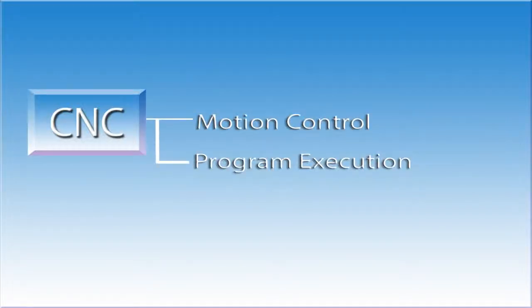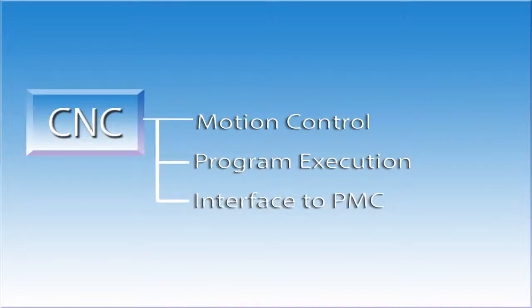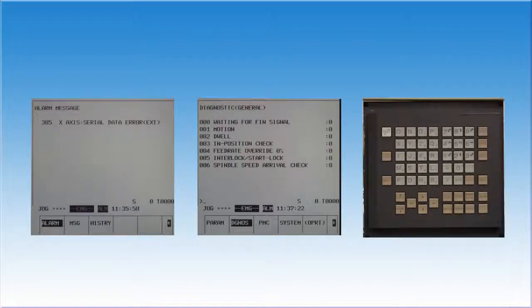This brings us to the third area of responsibility for the CNC: the interface to the PMC. The CNC and the PMC are always talking to each other. The CNC tells the PMC what its status is, and the PMC tells the CNC what is going on in its world. A large part of diagnosing machine tool problems lies with understanding this interface. The last area of responsibility for the CNC are the auxiliary functions. These include items such as CNC alarm codes, the display unit, diagnostics, and the MDI keypad interface.